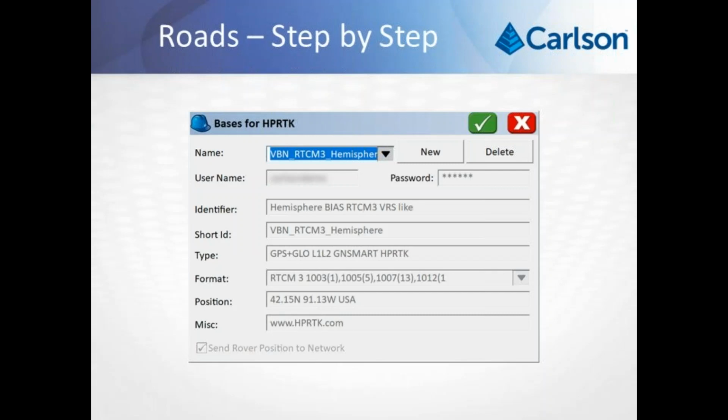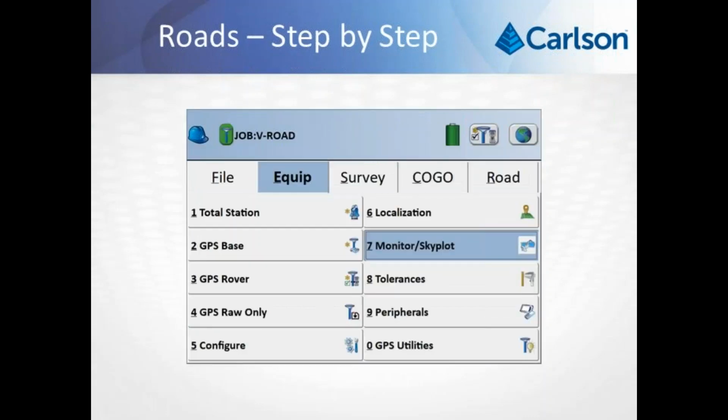And then the name of the bases that you want to use for that particular network. And then once you've gone ahead and selected that, you can connect up to the network, and typically before you get too far into your project site, you want to make sure that you actually have a fixed solution.